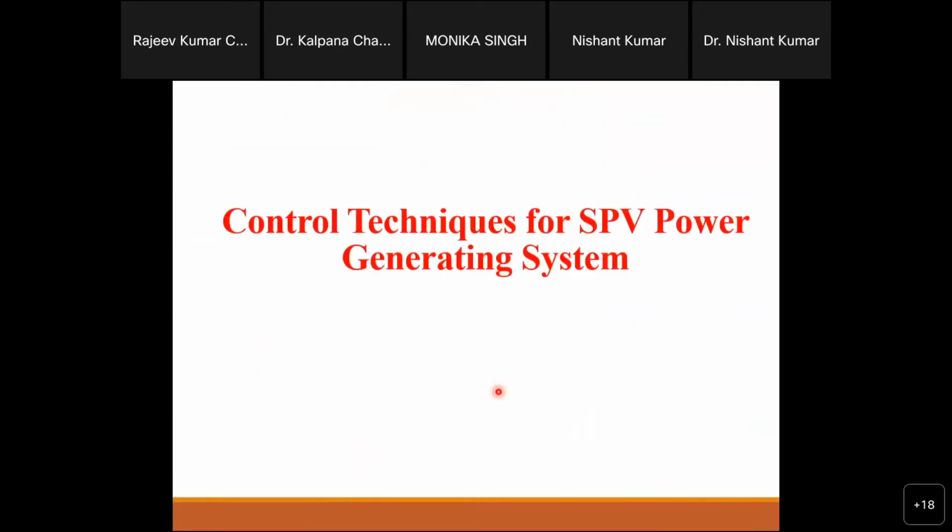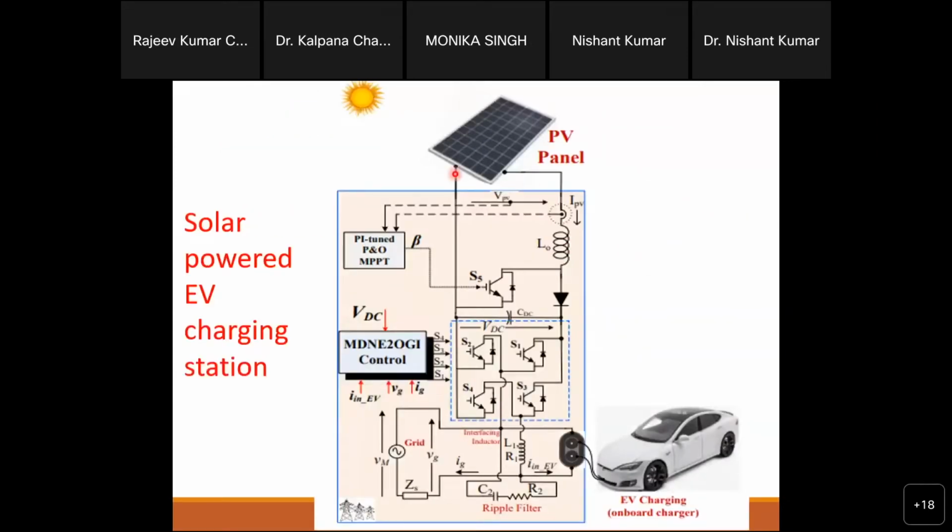The main purpose is at night time, when solar will not be there and the vehicle will connect. So what we will do, we will sense the nonlinearity requirement of this converter, these connectors or these chargers, and we will intentionally generate those harmonic currents and feed them, so that only the active power will come from the grid, and all the rest of the nonlinear current will come from the converter side. So in this way we can handle those things.